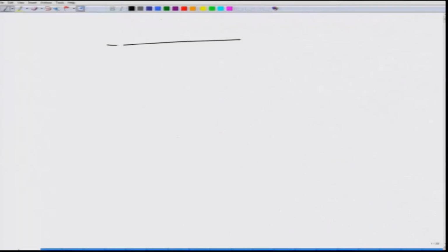Compared to binary phase shift keying, in which you can write down the constellation as consisting of 2 points which are separated by a certain distance, let us say this first point is located at square root of Es, the second point here is located at minus square root of Es. Remember, this is the I and this is the Q component. This is the complex signal space that we are considering, and these 2 points which are marked by the cross marks correspond to symbols 0 and 1.